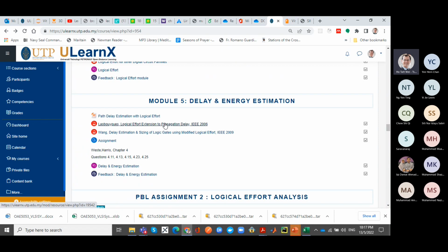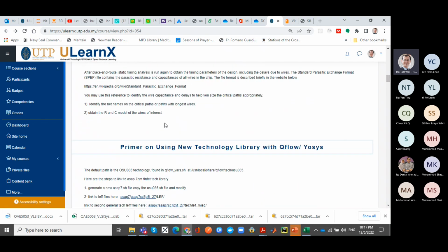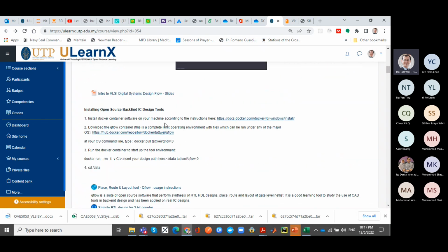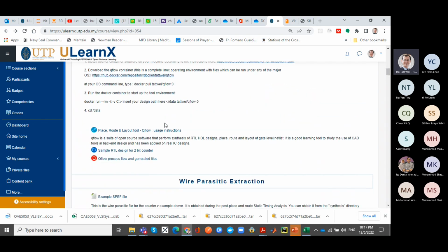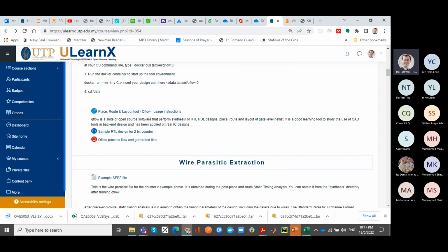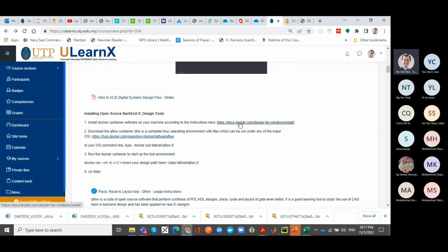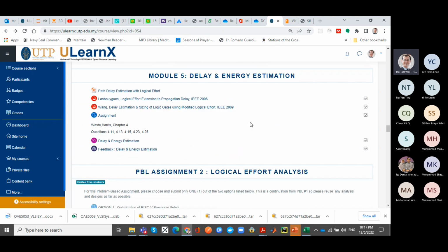So when you do the synthesis and the place and route, the software tool will give you a ranking of the top critical paths, from the worst case all the way to the best case. That's why I provide this tool for you here, so that you can see this in practice. The software will spit that out, and you can trace it, find out what all the logic gates on that path are, and then apply that analysis there.